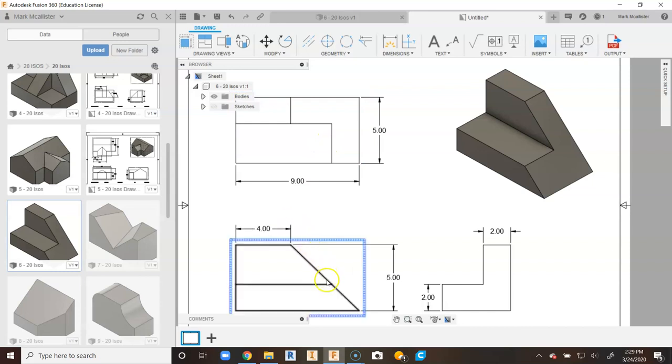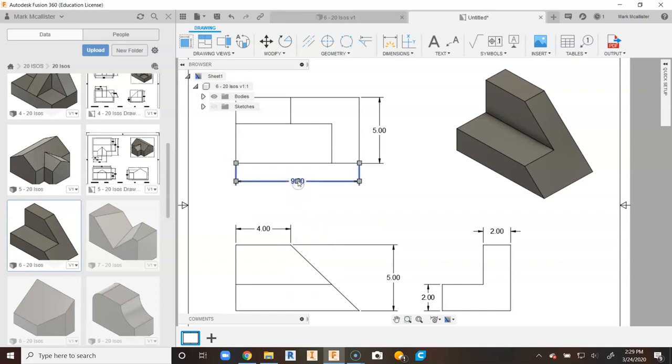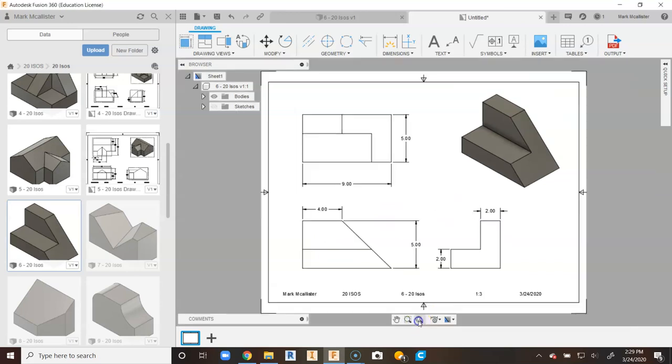Now we have not dimensioned this line down here, because you'll notice that when we come in and dimension it, that was a little bit out to a specific point, because we drew a line and cut. You notice that's a distance of 7. We could place that in the top view if we viewed that as absolutely necessary. I always view that something is completely dimensioned when it's dimensioned in a way that otherwise you have nothing else left to place and the person could still build it.